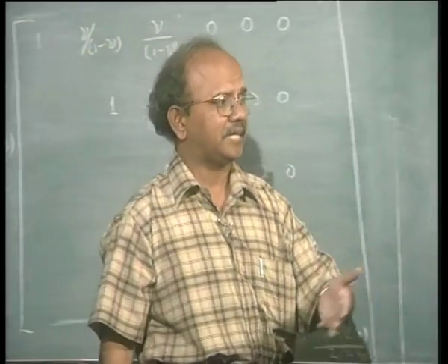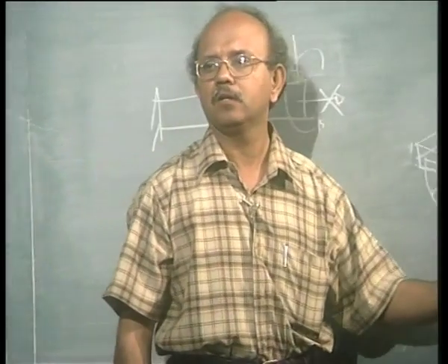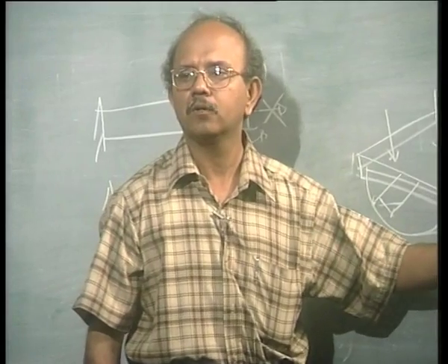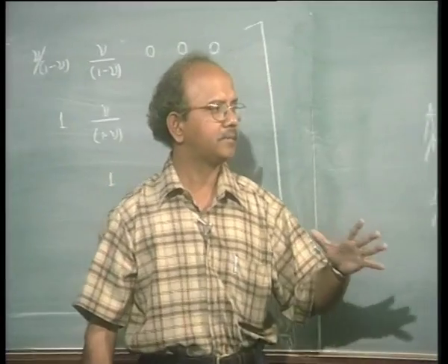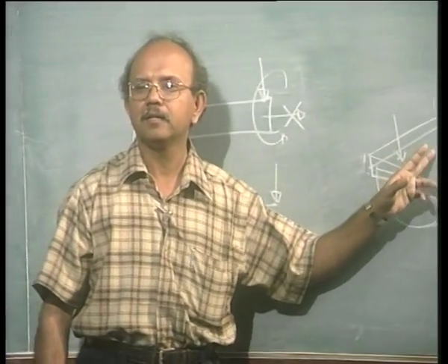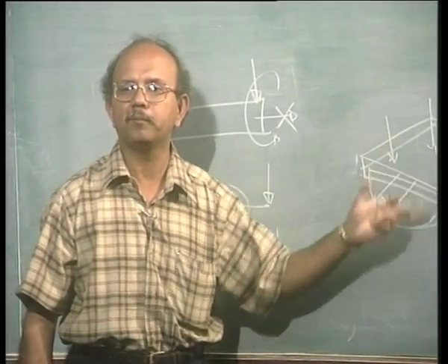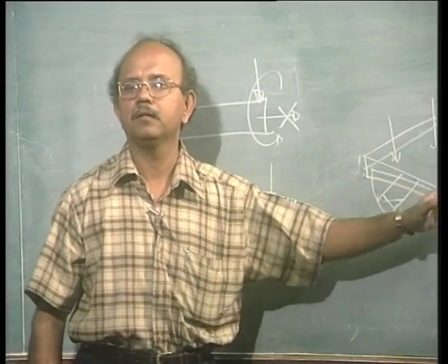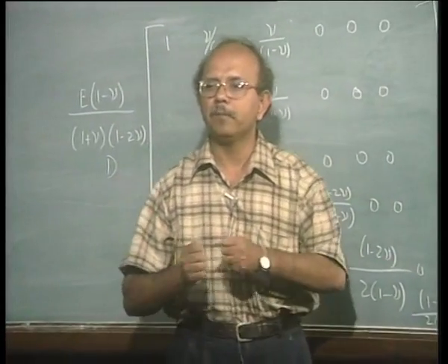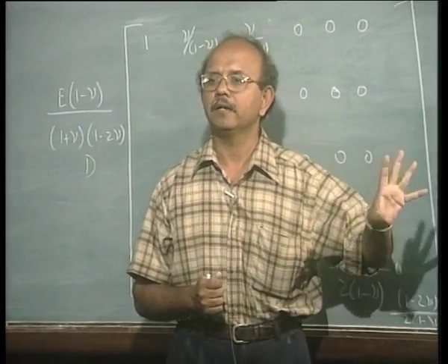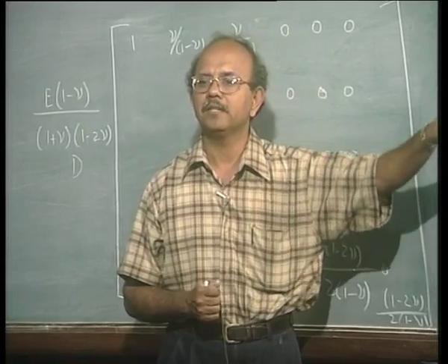The shell looks exactly similar to a plate, but there is a lot more theory to shell. Nevertheless, at this moment, in order to model, it is important to understand that when there is out of plane bending, and when there are loads that have to be taken in plane, what are called membrane effects, then I would look at it as a shell.